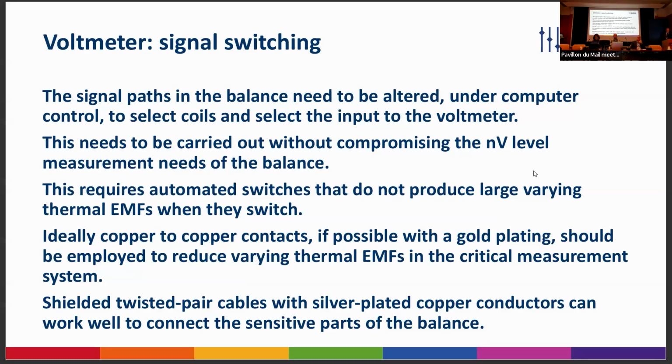In the past, Brian and I made modified relays. They were power relays with copper contacts. What you did was drill a hole in the back of the copper contacts, stick a copper wire in it and hit it with a hammer. That sealed it up, and gave you relays that would switch pretty quickly at nanovolt levels, but they were horrible to make.